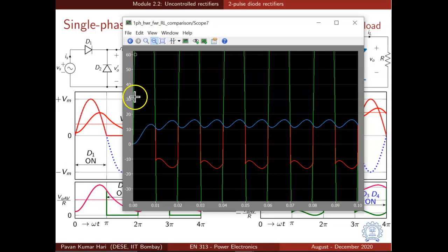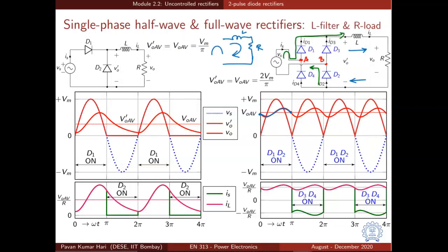Then what will happen? Since the diodes D3 and D4 start conducting now, why? D3 will come into picture because the inductor current is still positive and the VAB voltage has gone negative, so the current flow has to be there, and for that condition of positive current flow and VAB being negative, we know that in the common cathode connection D3 should conduct as soon as VAB becomes negative.